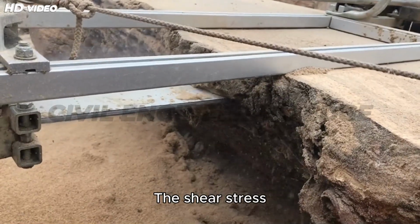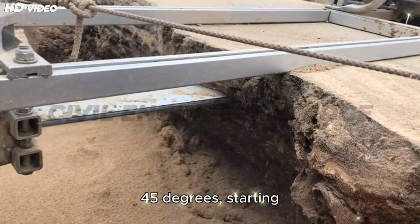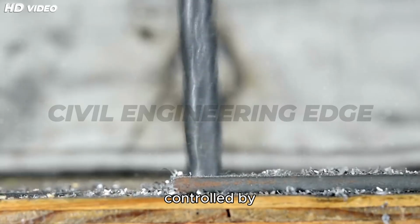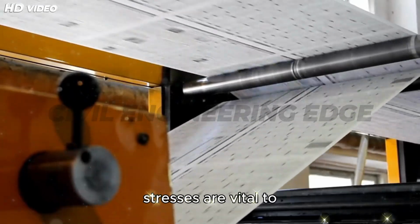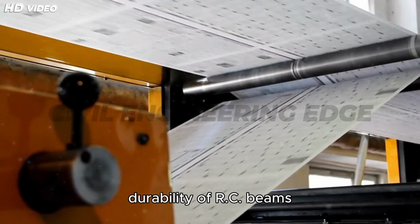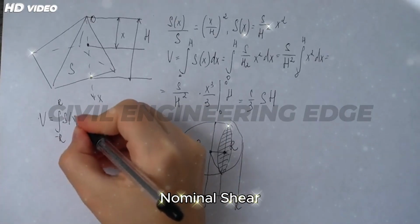The shear stress leads to inclined cracks, typically at 45 degrees, starting from the supports. These cracks are controlled by providing shear reinforcement like stirrups. Proper understanding and design against shear stresses are vital to ensure safety and durability of our RC beams under service and ultimate load conditions.